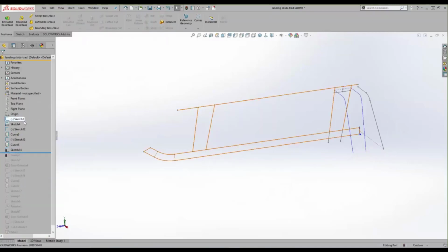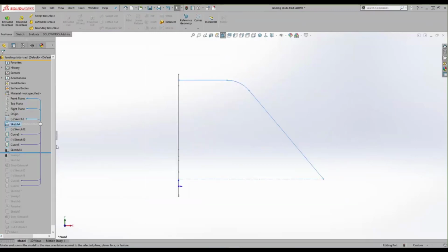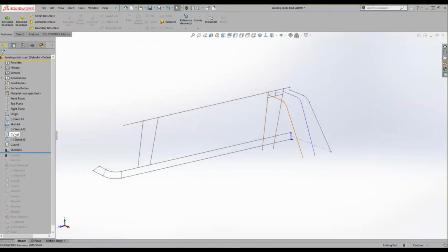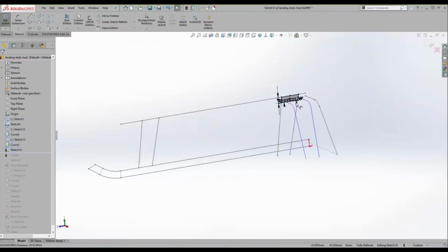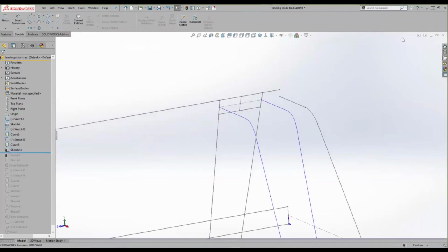You'll see they will share the same common sketch 1, that side profile that I'm looking to capture, as well as they will both capture this same sketch number 2 for the width of the landing gear. Now, in order to adequately control the geometry, again, I needed a guide curve in the front, extra sketches using convert entities, the guide curve in the back, a sketch with the appropriate sweep profiles and dimensions so it doesn't become underdefined and it doesn't, quote unquote, do anything odd on me.